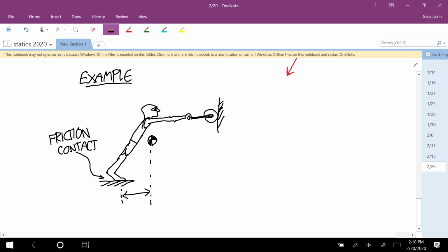By the way, we'll get into distributed loads pretty soon, but treating weight like it acts at a single point at your center of mass is an equipollent system. Gravity doesn't just calculate where your center of mass is and apply a force there. What it does is it applies a little force all over your body, and calculating the center of mass and applying the whole thing like it acts at the center of mass is just an equipollent system. Okay, so this distance is 0.5 meters.